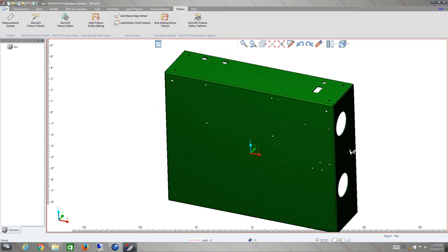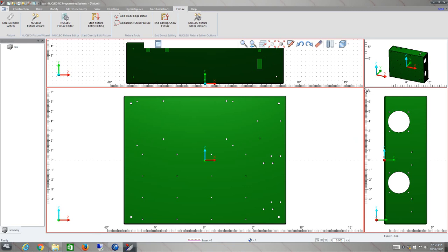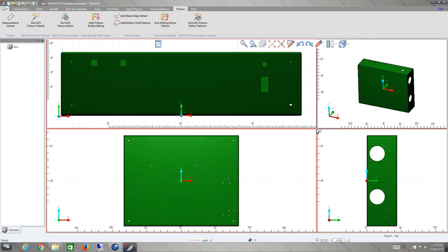So pretty simple. At the top of the screen we have our common icons, magnification. This one here toggles between 4 views. So this is basically my 4 different views of the same component. I can then click this again, and then the prompt line comes up, and because this is the active viewport, it's saying select the viewport.